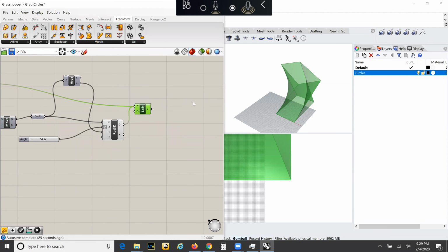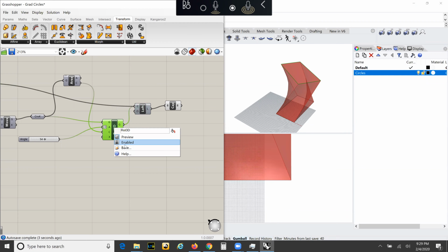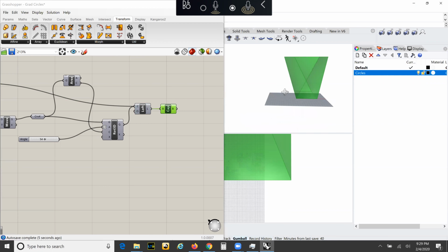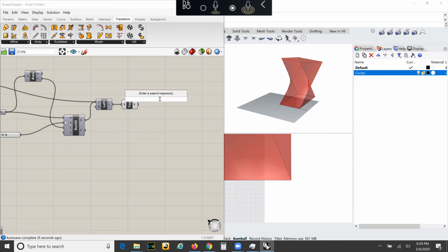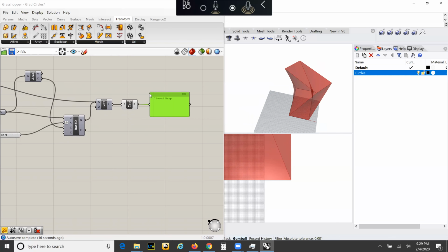We also can cap this. The great thing about Grasshopper is a lot of the times, and I wouldn't say all the time, but a lot of geometry it produces is watertight. So later on when we want to 3D print this, which the geometry that we are going to be producing in assignment 2B, we will be 3D printing. So it's key that when we cap it, we put a panel, it says closed BREP, which is really important, that word closed.